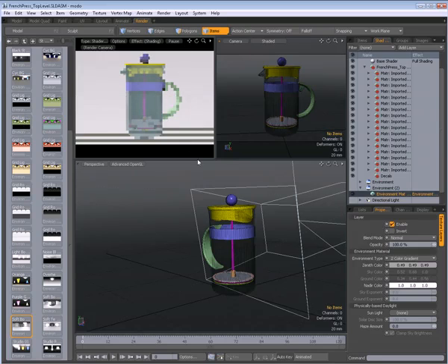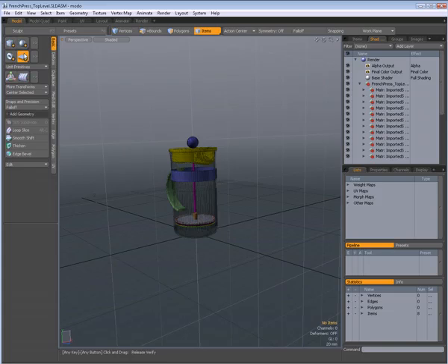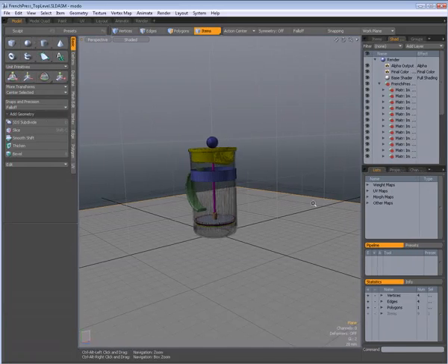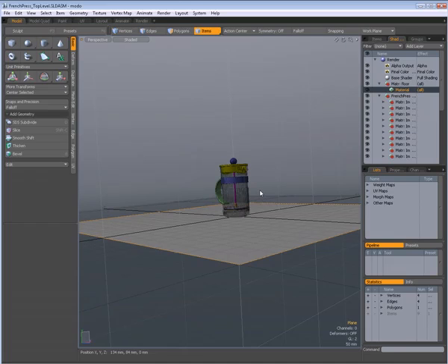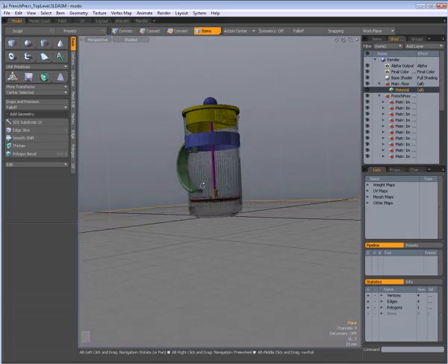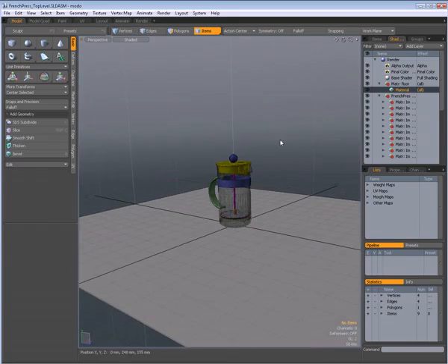That should give us a nice ramp from top to bottom. Makes it a little more realistic. Go back to my Model tab. I'm going to throw in a floor by shift-clicking on the Plane tool, and hit M for Material. Call it Floor. I'm also going to move it down just a smidge. Hit the W key on the keyboard and just eke that down a touch.